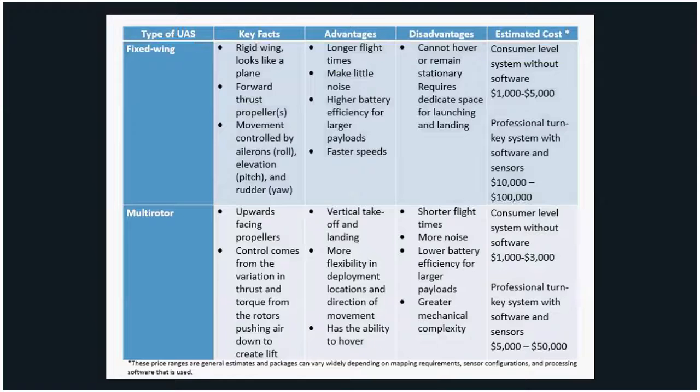Thank you so much. And then if you didn't use an RTK system, does anyone know on the order of what your accuracies would be? My experiment was without an RTK system. Oh, okay. So that's the 10 to 20. It was using survey ground control points in the field. So I think you would have to do one or the other. I don't think that you could get the accuracies that you would want just from using the GPS from the sensor on the device if it wasn't an RTK system. Okay.